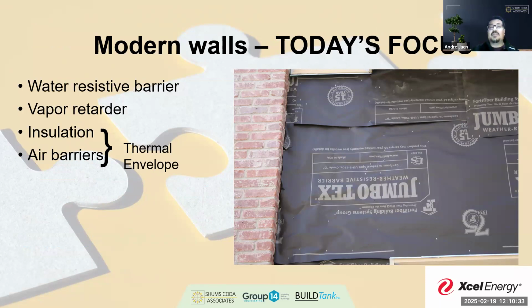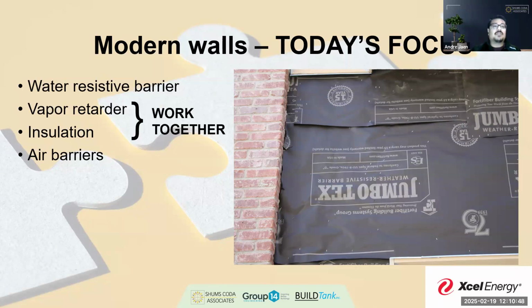To make sure that it's properly buried to be fully within the thermal envelope in those places that abut outside or an unconditioned space, right? It's telling you that you need the continuity of both your insulation and your air barrier in those places. That really does produce our thermal envelope.